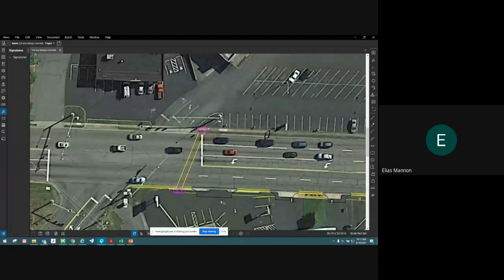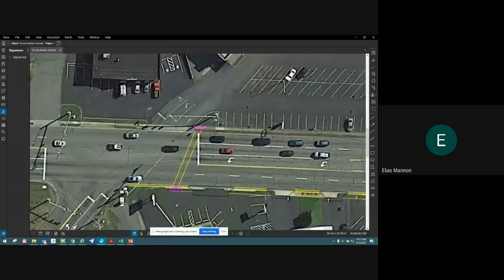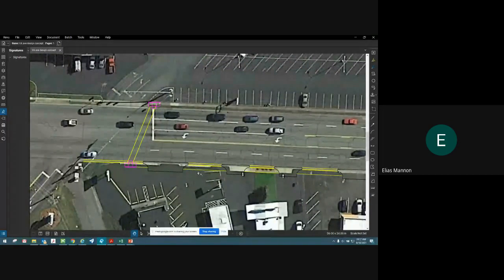This intersecting street is called Wheeler Avenue, near the Dutch Inn Plaza, near Collinsville, if you're familiar with the area. The proposed solution was to install sidewalk along the lower side of the road here. That's the west side, but plan bottom. There's existing sidewalk on the other side of the street, and the proposed improvements were to install curb ramps, crosswalk, and ped actuation and signals in this area.